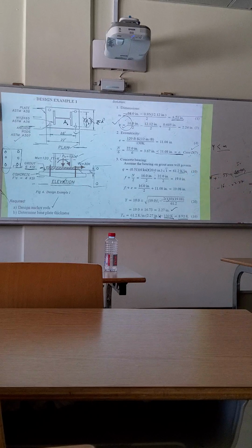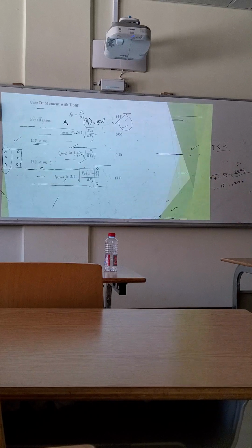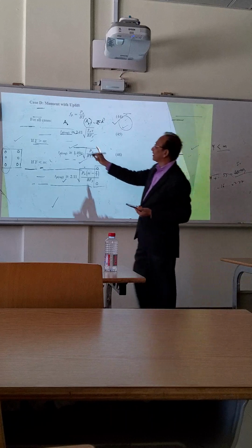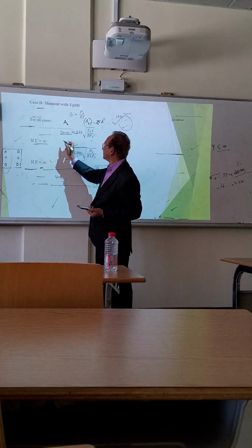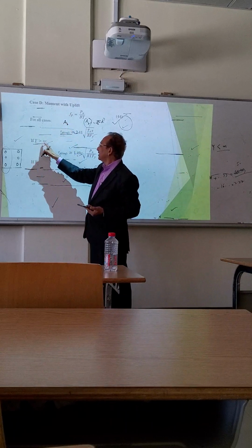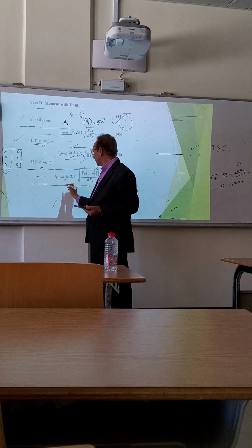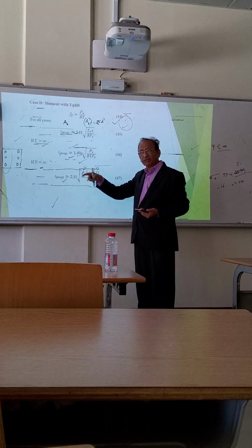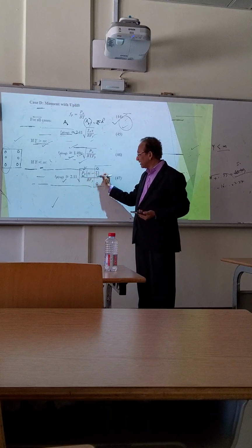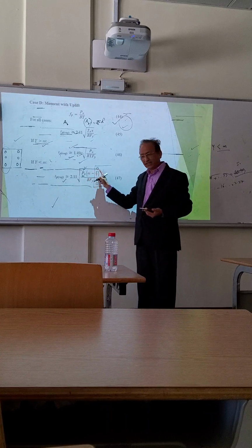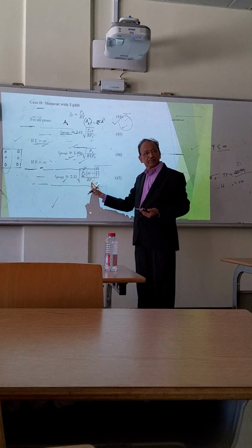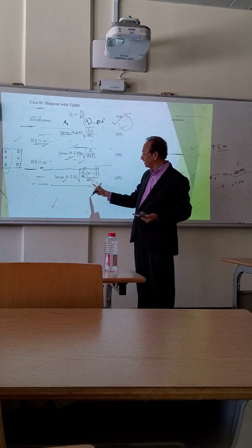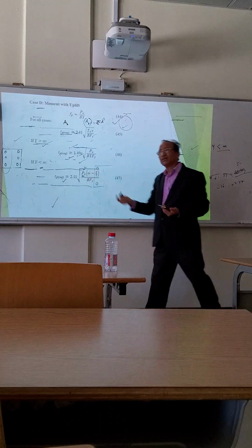Now once you have finalized that this is case D, we come back and check the formula for case D that will be used for a plate like this. Y greater than M, this formula. Y less than M, this formula. So 2.11 times Pu, you know the value of Pu, it is given. M minus Y by 2, you also know M and Y. B into Fy, you have calculated the value of B, it is already given, and Fy is also given for the plate.